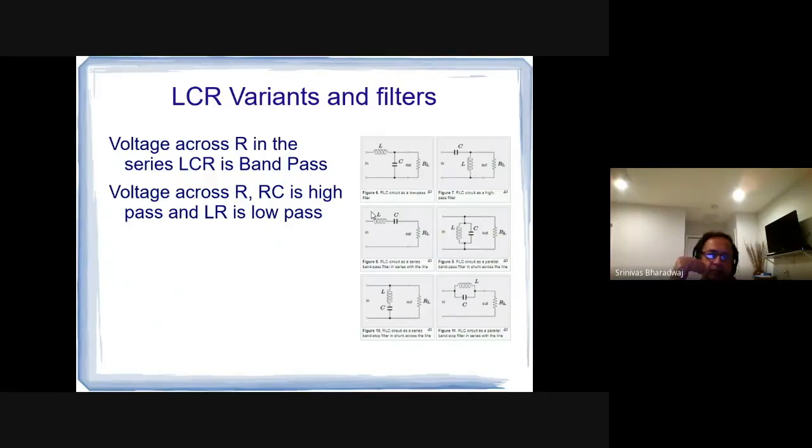And now, why does that help? Remember, this is kind of like a resistor, and you want to maximally absorb that power. How do you do that in the context of a particular circuit? There are so many different combinations between an L, a C and an R, not just the single series combination. This combination will be a low pass, so at lower frequencies there will be maximum power across RL. This combination is a high pass. When it's a high pass, at higher omegas there will be maximum power across RL.